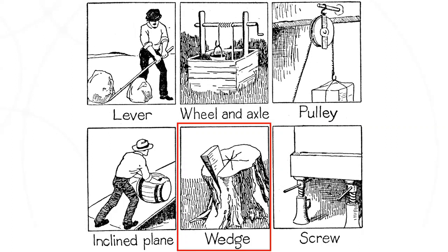As you come in and you're compacting and putting the material under the haunch, and you're using your impact machine to compact that, what's it going to do to that pipe? It's going to want to lift it up. It's going to act as a wedge underneath that haunch. So the more we compact it, the more it's going to lift that pipe up, and it's going to act as a wedge to get it off of alignment.